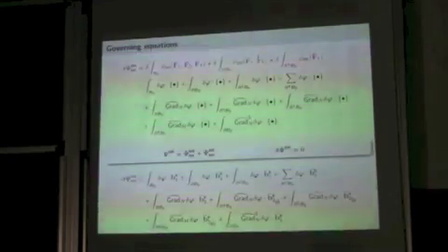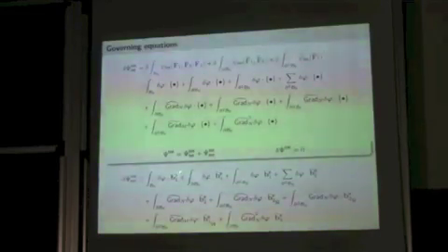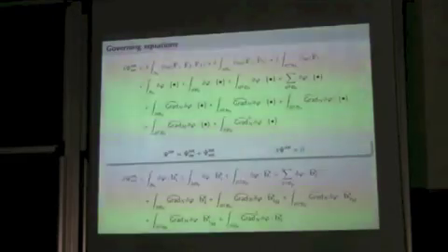Now, we want to set the variation of total energy to 0. This is the next step of this recipe of Mindlin, basically. So you set up an external energy or external potential which fits to your internal one, and then you get sort of the proper boundary condition, if you like. Now, if you look at the first integral, this is an integral over the bulk, and this B1 is the energy conjugate to the displacement in the bulk, so it's basically your body forces. I use the P to denote it's prescribed.